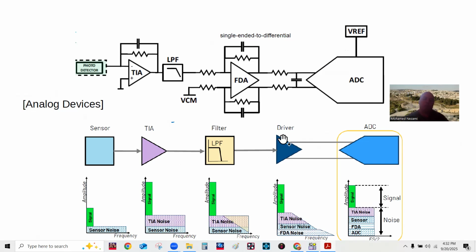Now, you cannot get free noiseless amplification. That is always the case. So how do we go into that next? I'm going to try to model this so we can look at the noise. And right when you start looking at the noise, we're going to get into the aspect of noise density for these devices. So we do have the noise density for all these devices, and for the ADC, we have to look at its noise density as well.